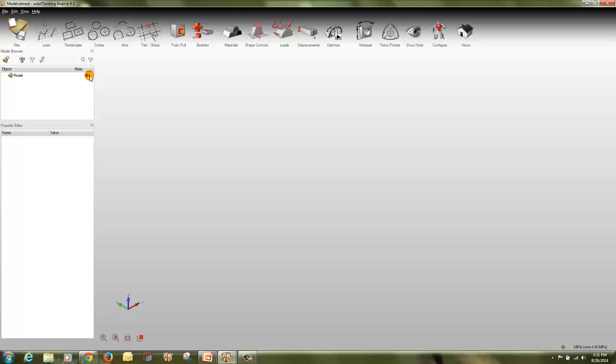So the push pull faces tool is used to push or pull flat or cylindrical faces created with the sketching tools. It can be used to extrude solid from faces, create or resize holes, modify or eliminate rounds, and modify wall thickness. This tool is useful for defeaturing a part to make it suitable as a design space for optimization. Pushing and pulling without snap. As you push or pull a face, a ruler appears showing how far the face has been pushed or pulled. If you have snap enabled in the preference window, so edit preference.